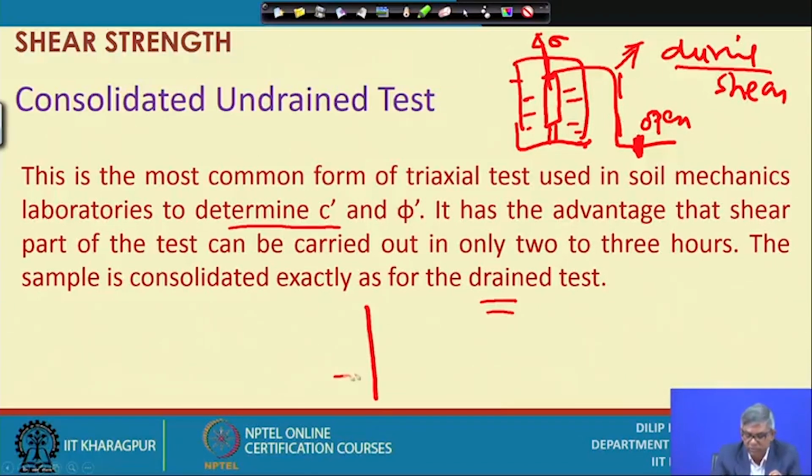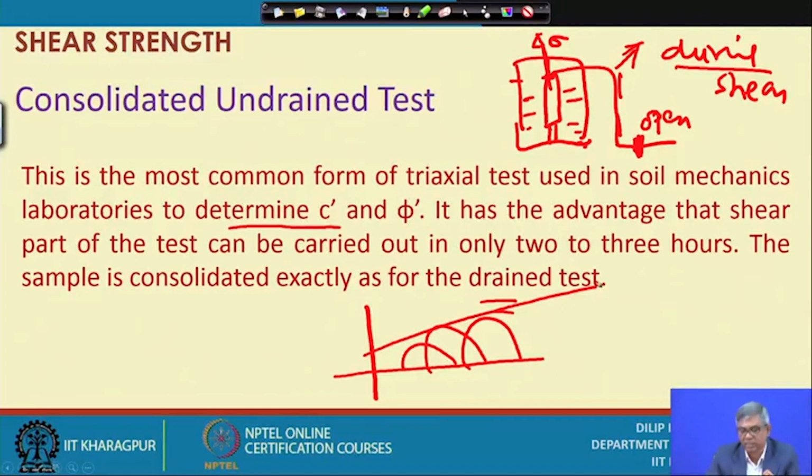Suppose based on total stress, we have got some circles like this, and we have got a tangent. This is based on total stress, without subtracting the pore pressure. We have drawn three or four circles, with sigma 1 and sigma 3, and drawn a common tangent, from which we get a C and a value of phi. So, that gives you the total stress parameters.